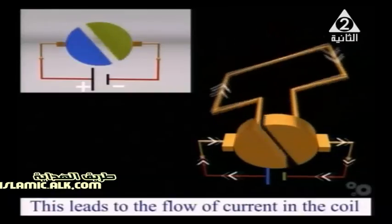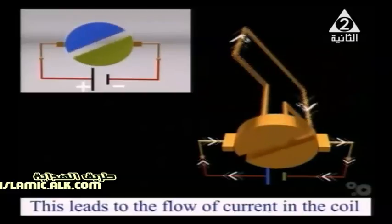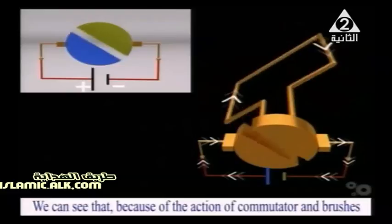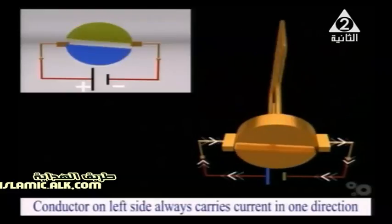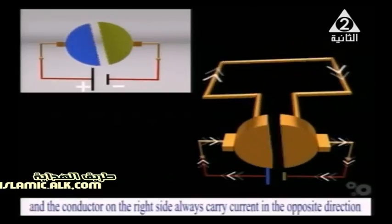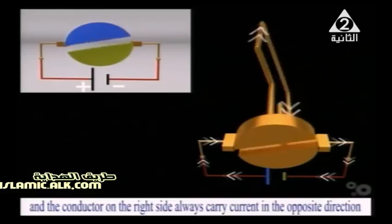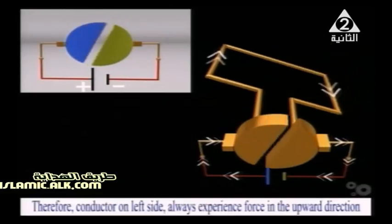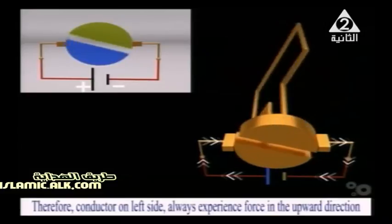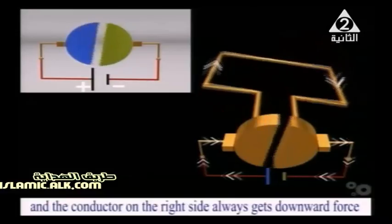As the coil rotates, the torque of the couple decreases until it becomes zero when the plane of the coil is perpendicular to the magnetic field in the vertical position. But as I said, the coil continues to move by its own inertia. When the coil just passes the vertical position, the two halves of the commutator switch over.